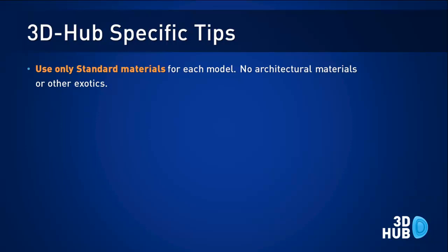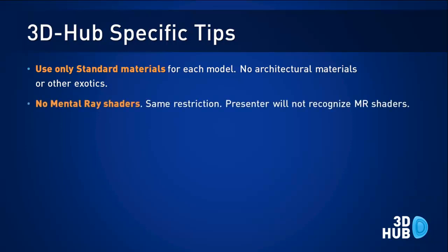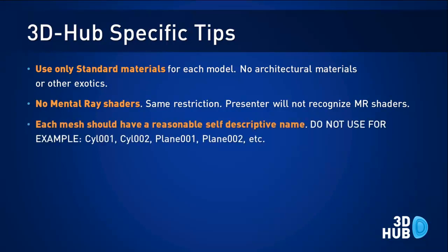We don't support architectural materials. If you do use the architectural materials in 3D Studio Max and try and export them, you normally just get an error, and if you don't get the error message, then the material certainly won't be reproduced in the 3D-Hub player. Again, that works with mental ray shaders, V-ray shaders, that they're just simply not supported. It is really just a standard material, 3D Max materials. We do support DirectX shaders. That's another topic that we will cover at a later date.